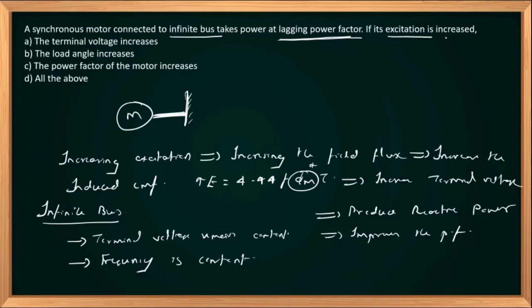If its excitation is increased, does the terminal voltage increase? No. Does the load angle increase? No. The power factor of the motor increases. The power factor of the motor is increased. Option C is the answer. Option C.